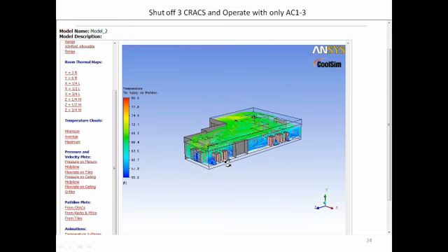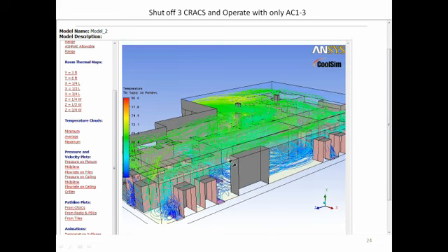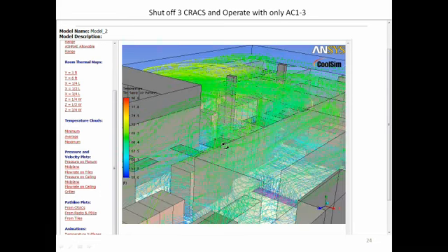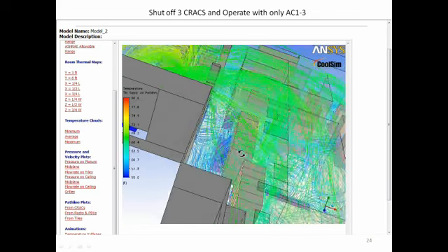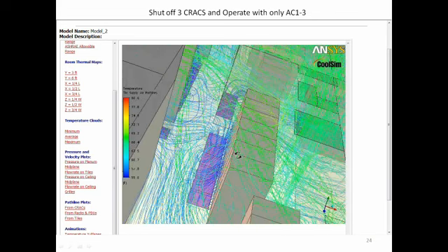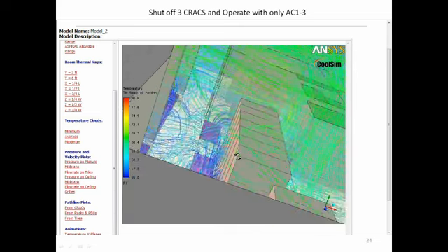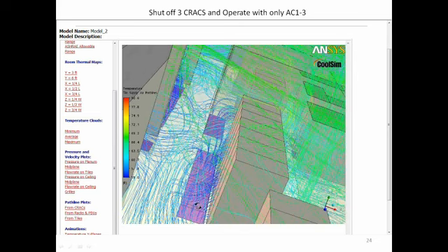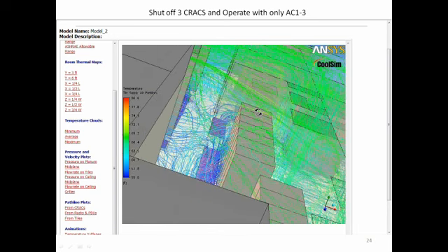So the ones on the lower left, it's a nice illustration. If you zoom in and turn it a little bit, you can see how. Yes, this is how it's supposed to work right here. This is what she's talking about. A couple of those places. The air is supposed to come up out of the tile and go right into the rack. So here's an example of it behaving properly. And at the very end of the room, you can see it as well. Yeah, it's right down here. That's how it's supposed to work.